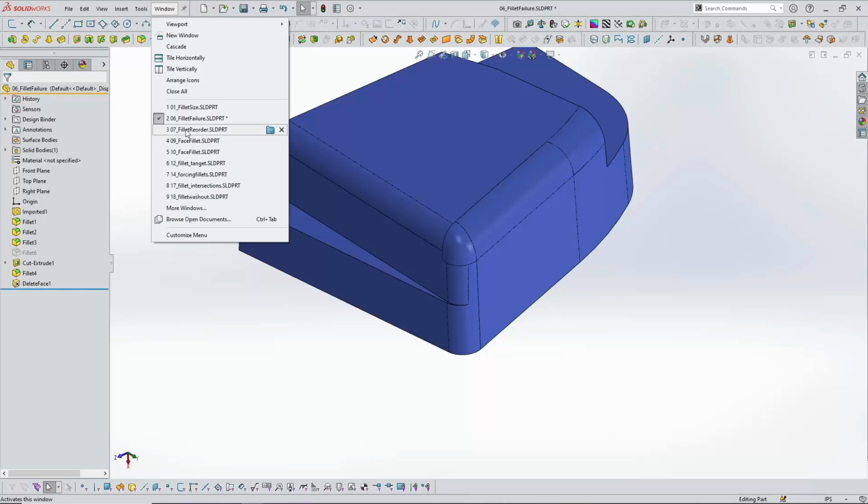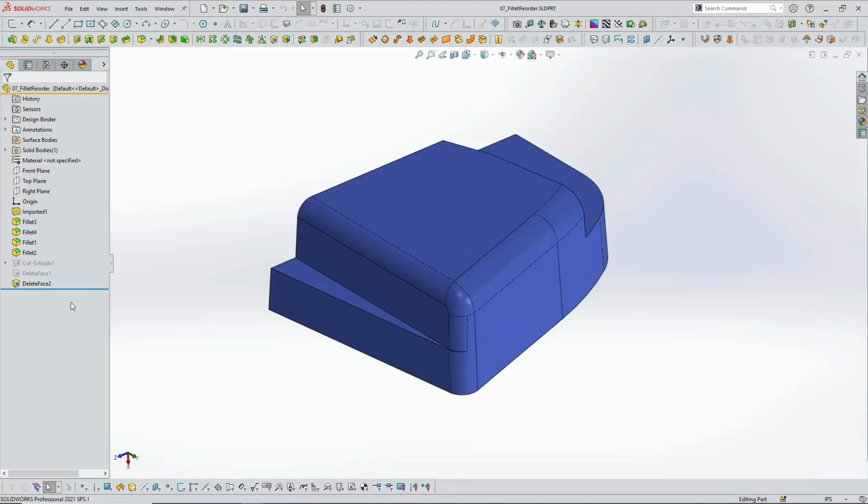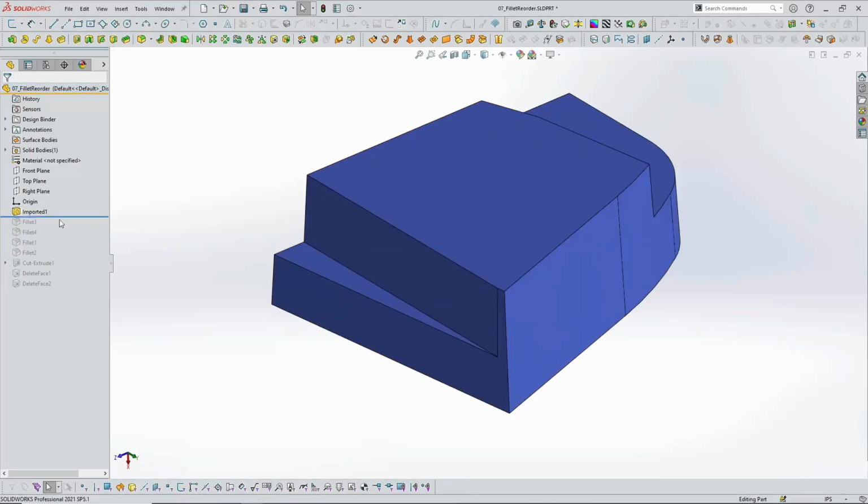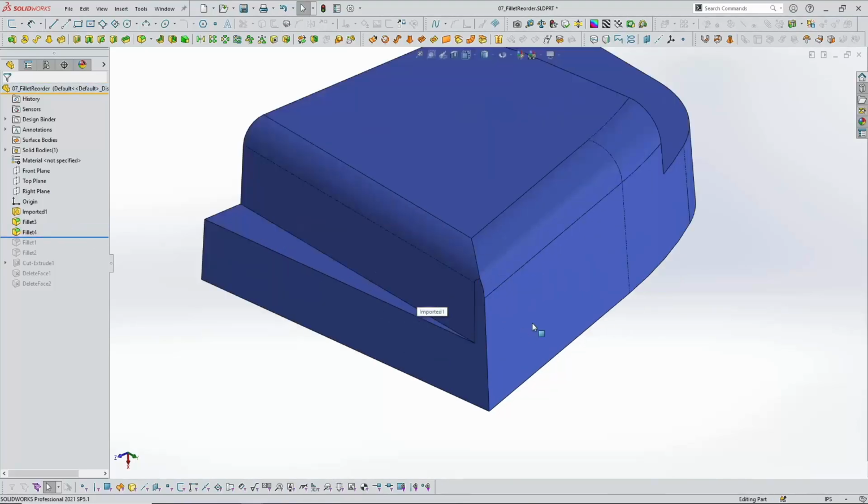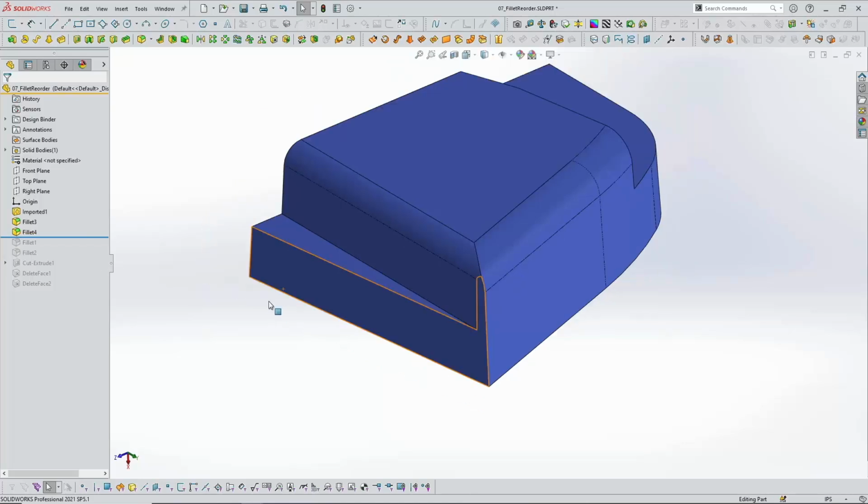Likewise, the next little bit of fillet diagnosing could be what happens when we reorder some of the fillets. And this would be if you had access to the model history, that it wasn't too much work to try and move things around in your feature tree. If you can do this, it's always potentially a little bit cleaner. And this speaks to the order that the fillets were applied in.